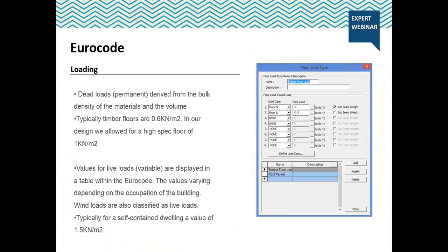Often in London, where masonry is involved, care is needed to make sure deflections of supporting members are kept to a minimum to prevent cracking to the brittle material. A maximum deflection limit of span divided by 360 is adequate for a steel beam supporting masonry, whereas for a steel beam supporting a timber floor, as is the case here, a maximum deflection limit of span divided by 270 is adequate.